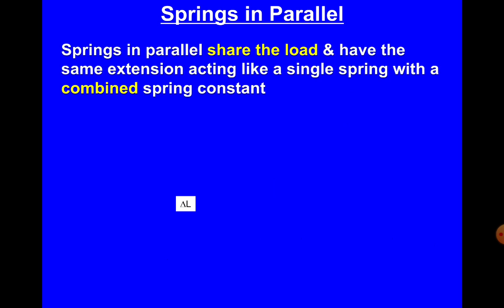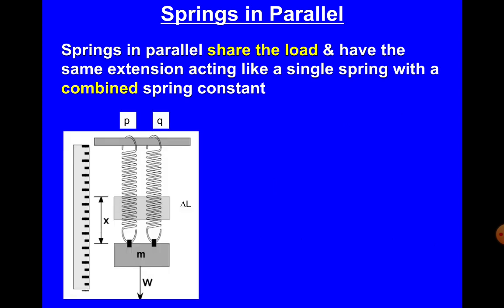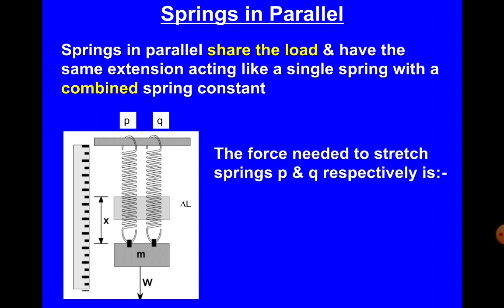What is going to happen when we put two springs parallel? Look at this experiment. Now we put a weight on two springs in parallel, so actually the load is going to be equally divided over the two springs. So what would you expect for the extension compared with one spring? Well, we can expect that the extension is actually half of that of one spring.